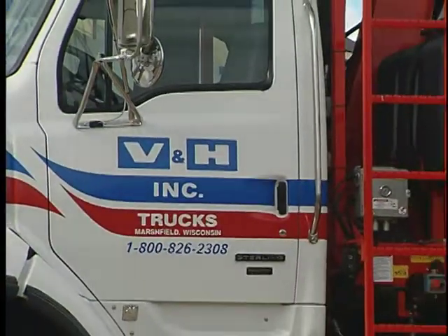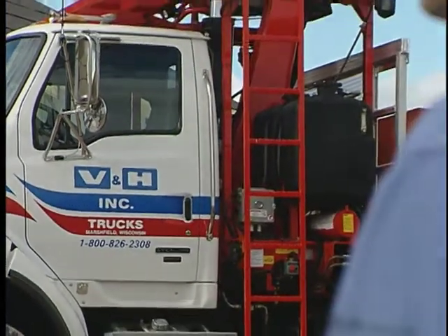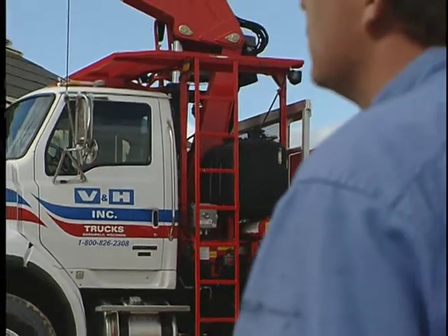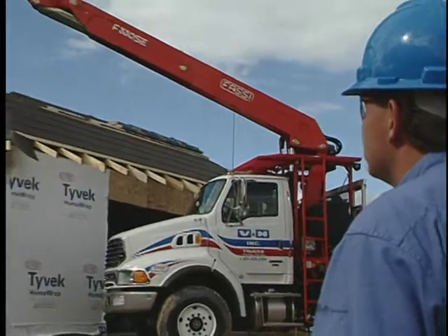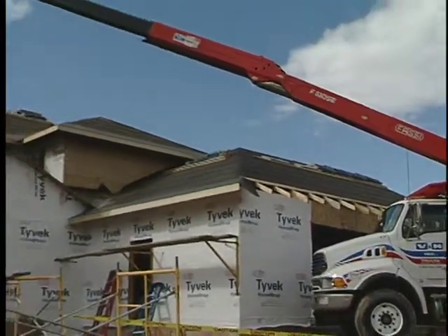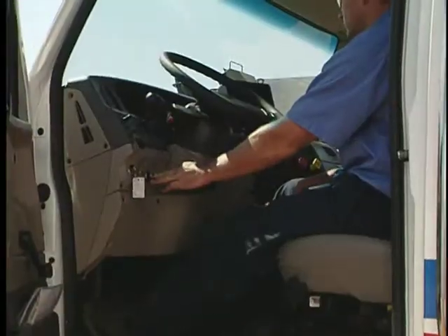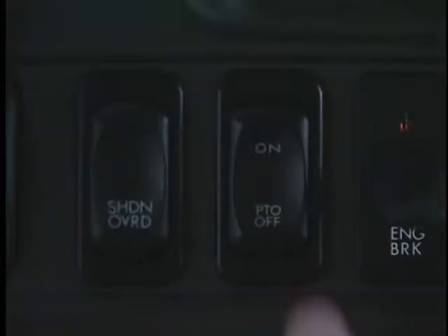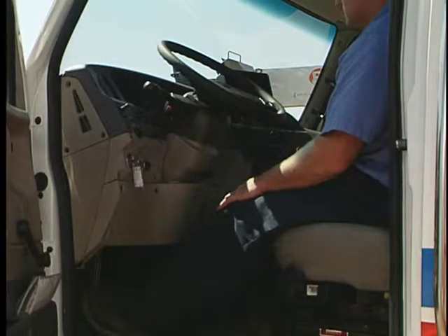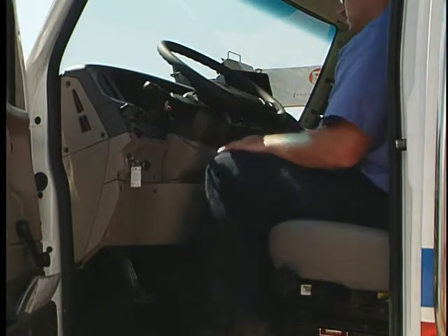The crane is powerful, productive, and efficient, but requires skilled handling. Understanding control functions helps you understand how the boom and fork work together. To begin, the engine must be running and PTO engaged. This powers the hydraulic pump. The crane is in idle and ready for commands.